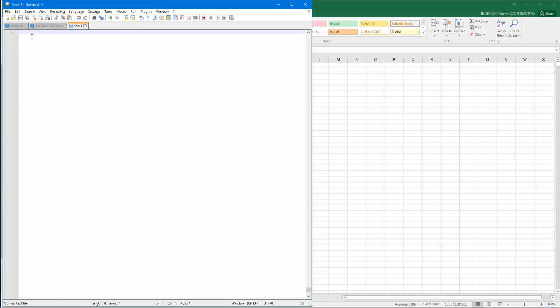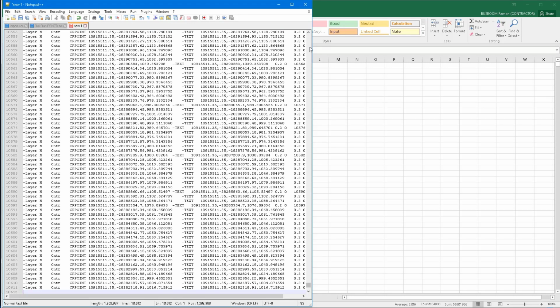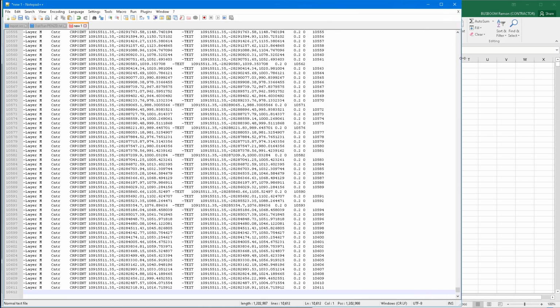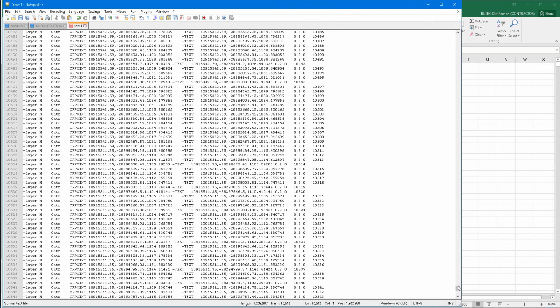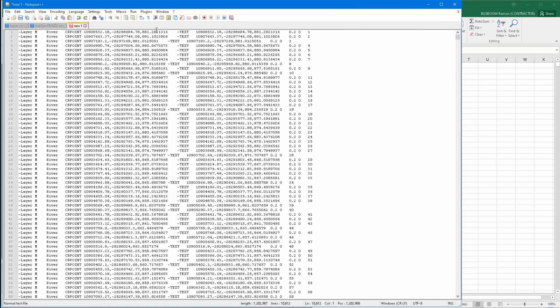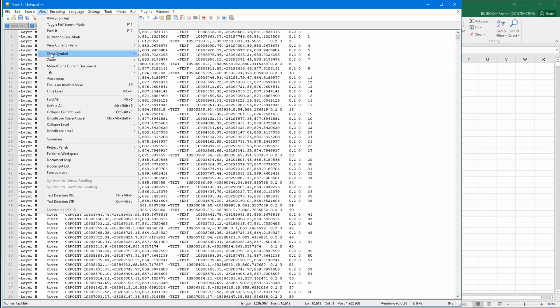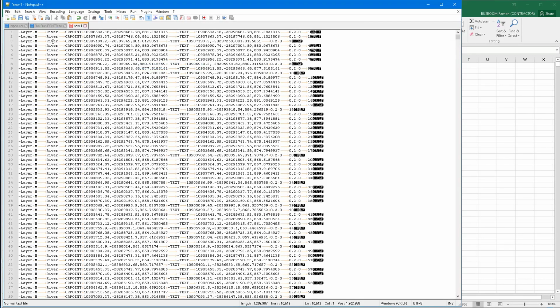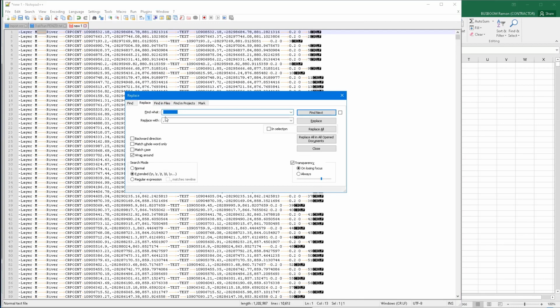And so in this particular example, and it's free, let me mention that, I'm going to just paste. When I paste it from Excel, Excel does a couple of things. Between its columns, it's going to put in a tab, and I can see that by turning on all the symbols. So I'm going to select one of those tabs and replace that with just a space, because I need the command to actually type in a space between these columns.